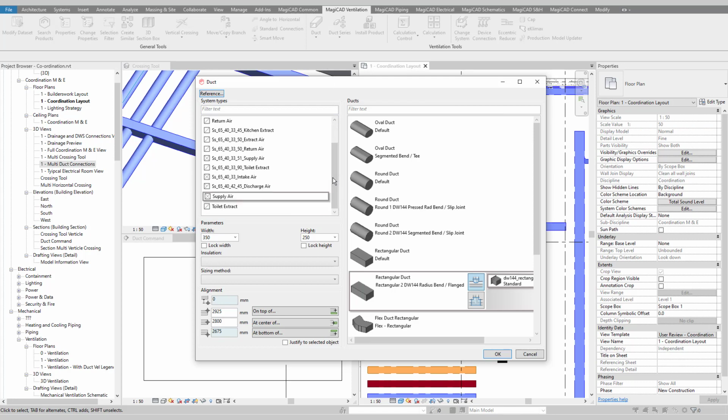You can also select your duct series, which are your duct families, and then you can also select your sizes of your ductwork, width and heights. You can also have installation series added to here, and also sizing methods that will be used in conjunction with our calculation tool. What you do have down here is a group of offsets.